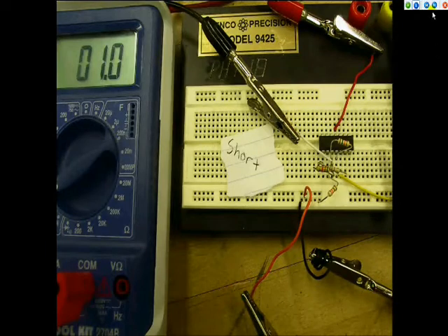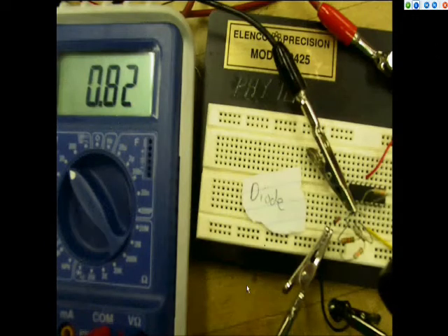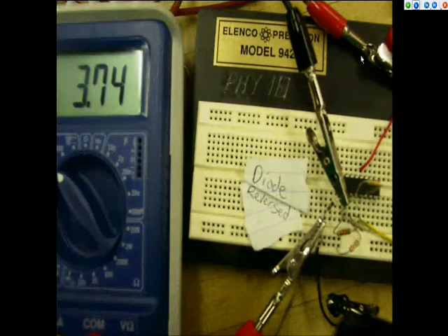And now when we put a Zener diode in, which is actually reversed here, at 0.82 milliamps is the current, so it looks like it couldn't sustain 1 milliamp, and the voltage at which it started to drop off for that reverse diode is 3.74 as we measured the voltage across it. So now let's have a look at the PSpice simulation and see what that can tell us.